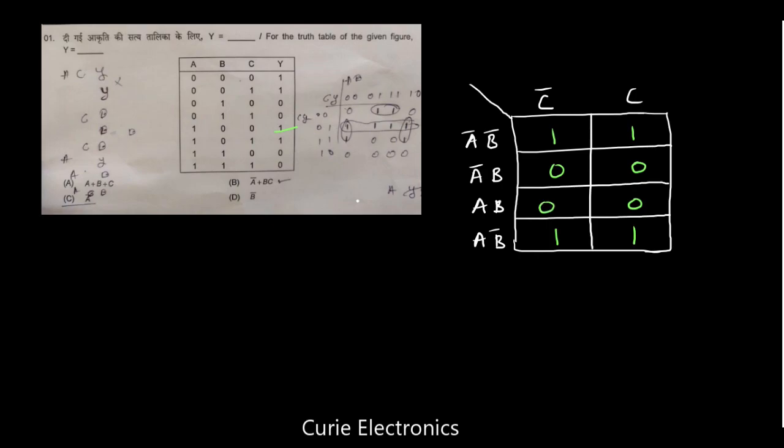So we can fold it. When we fold this, we will get a group of four variables, and two variables will get cancelled. Here C and C bar will get cancelled. Then A bar B bar and A B bar remain, so finally B bar will be the answer. So y equals B bar. See here, A bar B bar, and from the last one, A B bar. A bar and A will cancel. B bar is the answer.